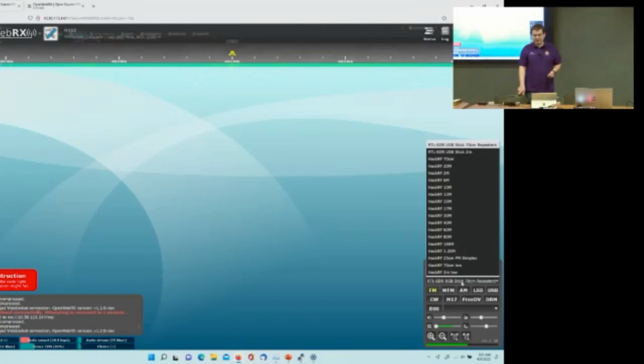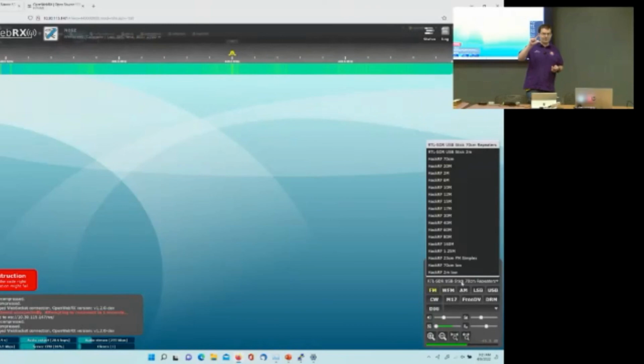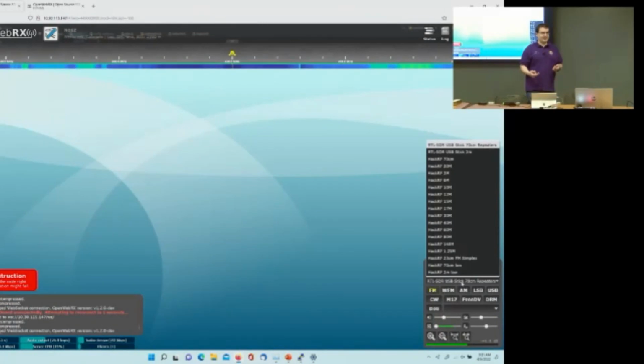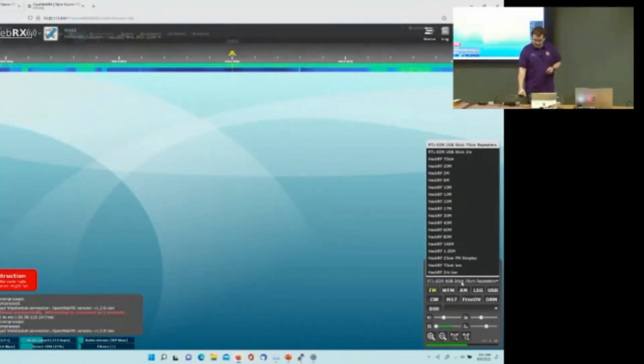This is actually a Pi 3. It has an RTL SDR connected to it and a HackRF. The HackRF has the real antenna outside on the tower. The RTL SDR has like 3 inches of wire stuffed in the bottom of a telecom rack. But that's interesting too, right? Because you can listen to the leakage off the coax and debug transmitters that way. But you do need to go through, and it's kind of a pain to configure every last ham band or other thing you might want to listen to.